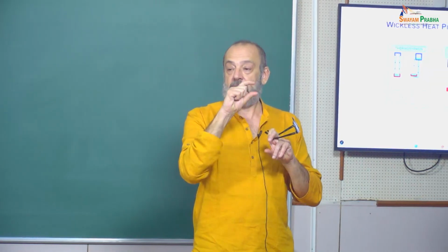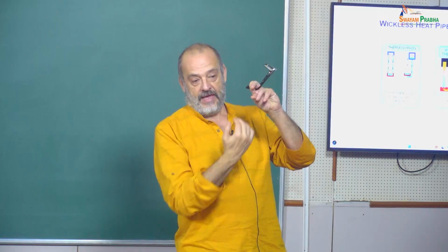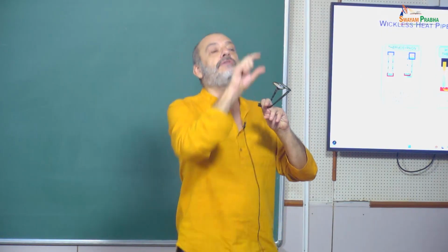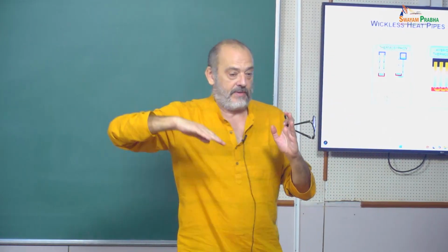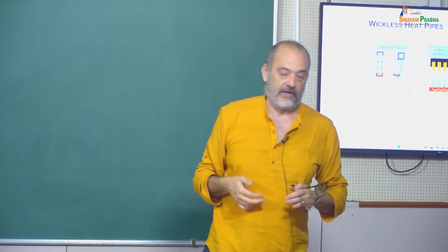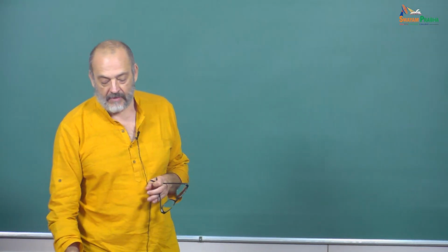So it's really something like a cork in a bottle. If we have an expansion of the vapor, then it's going to move the entire liquid. If it's a stratified flow, of course not, because the vapor will pass over, and then it's not working anymore. Okay? So these are the systems we are thinking about.